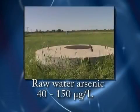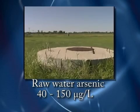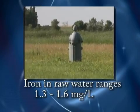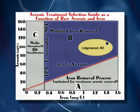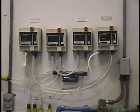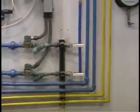The raw water arsenic concentration ranged from 40 to 150 micrograms per liter, predominantly as arsenic-3. The iron in the raw water ranges from 1.3 to 1.6 milligrams per liter. This puts the system in Zone B on the chart. The treatment in place before the EPA demonstration project included chlorination with gas chlorine for biological growth control on the filters and oxidation of the iron in the raw water.